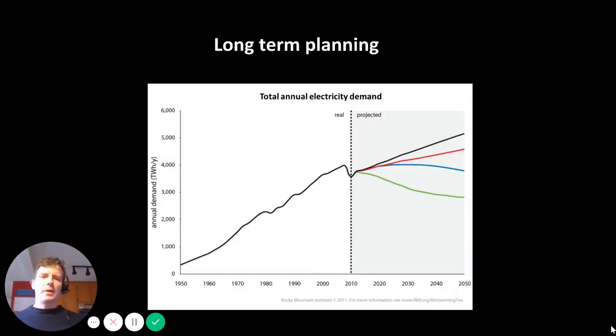So last time, I introduced this issue of timescale in long-term system planning. We talked about how decisions about how much generation capacity a system is going to have need to be resolved down to the hourly level. We have to know what the peak level of electricity demand is going to be in any given hour of the year, and be able to have enough generation to cover that and then some.